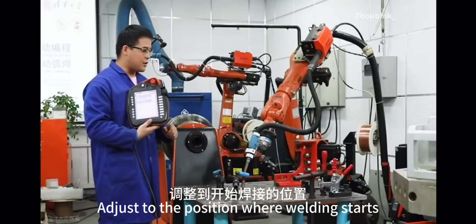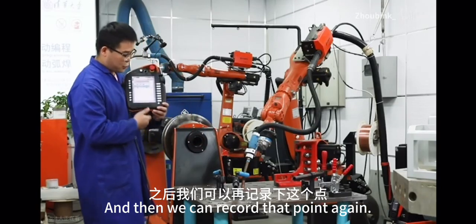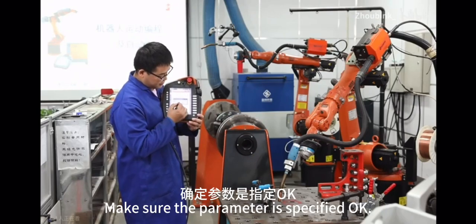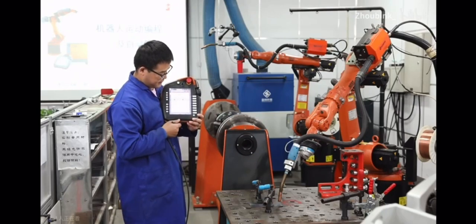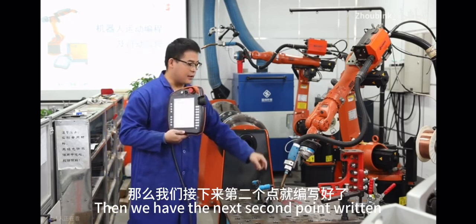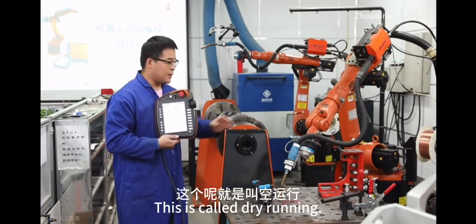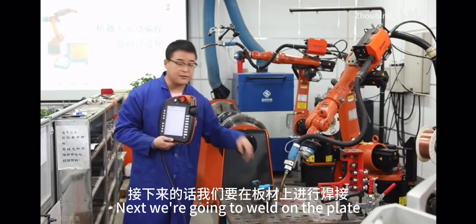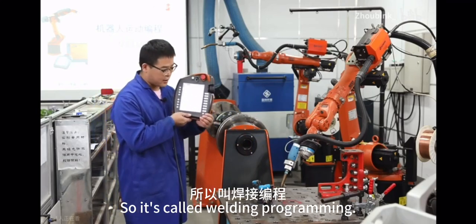Adjust to the position where welding we can start. Record that point again. Same as before, make sure the parameter is specified, OK. Then we have the next second point written. This is called dry running. Next we're going to weld on the plate, so it's called welding programming.